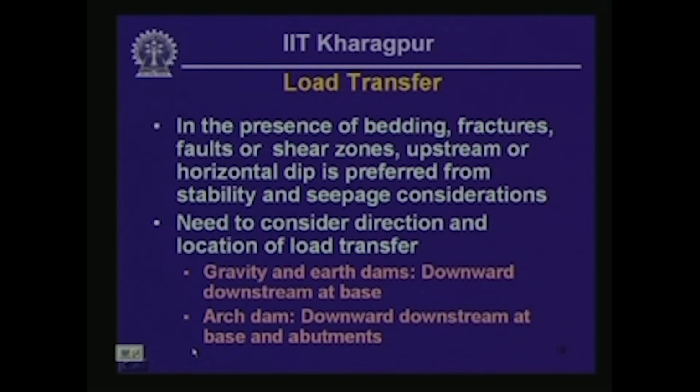Okay. Then we consider load transfer. The major points to consider here include whether there are bedding or fractures or faults or shear zones, and what is the orientation of these planes of weaknesses with respect to the direction of the water flow, whether they are dipping towards the upstream side or horizontal or dipping towards the downstream end.